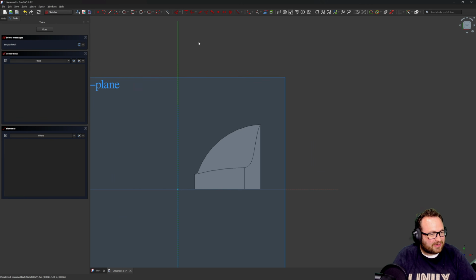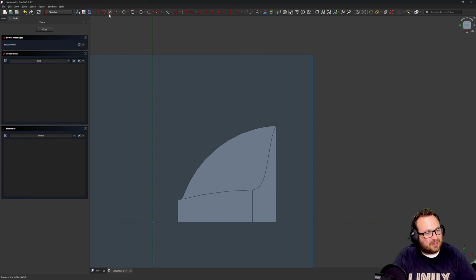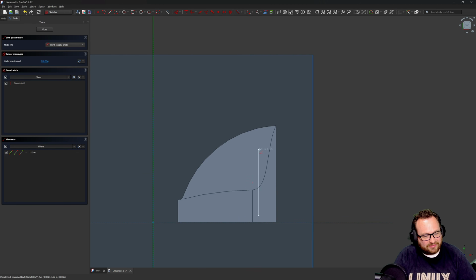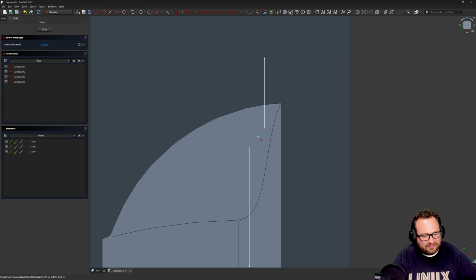So now that we're in an active sketch, I'm going to use this little face right here, of course, view section. And that will allow me to see my sketch elements as I start sketching. So there's a little 45-degree angle for the lug nut to butt up to. Right, I'm going to hit D for dimension, click both lines, and say 135 to make sure that that's the